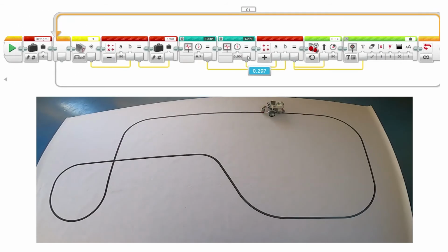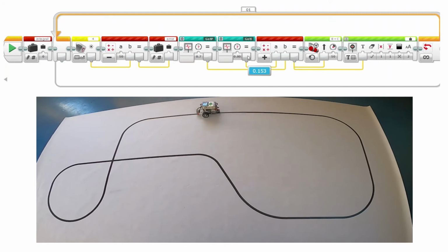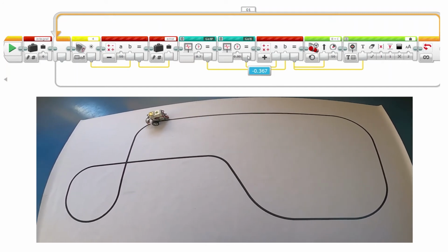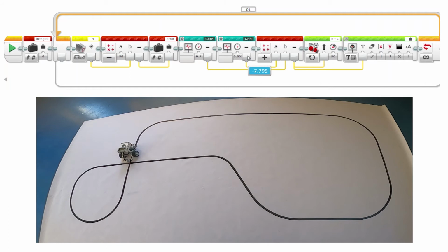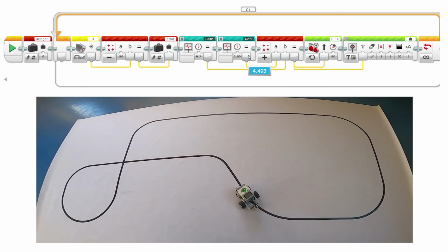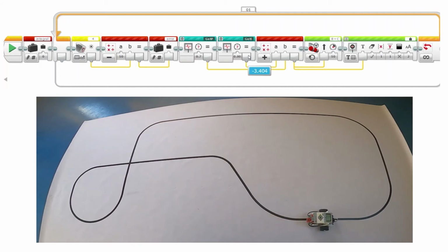getI. The integral part reduces the wobbling of the robot, and the robot can finish the track a few seconds faster. If you connect the robot to the computer using Bluetooth and run the program, you can drag the mouse cursor over the variables to see the actual values. Here is the demonstration of the actual value received from the getI block. Usually, the impact of the getP block on the steering value will be bigger than the impact of the getI block. If the block getI returns very big values, then probably the integral constant you have chosen is too big.